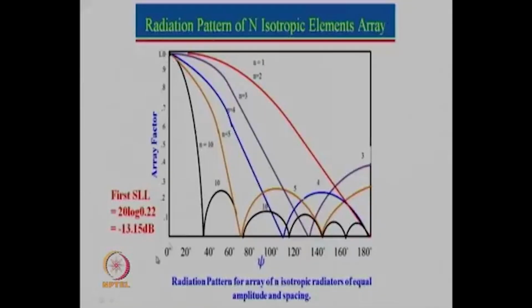So we are only showing the one part from the broadside direction. We can see that the half power beam width continuously decreases as we increase the number of elements. Say from the starting, if we draw our imaginary line here, then for n equal to 2 the half power beam width will be large, then it will decrease, it will decrease, it will decrease.